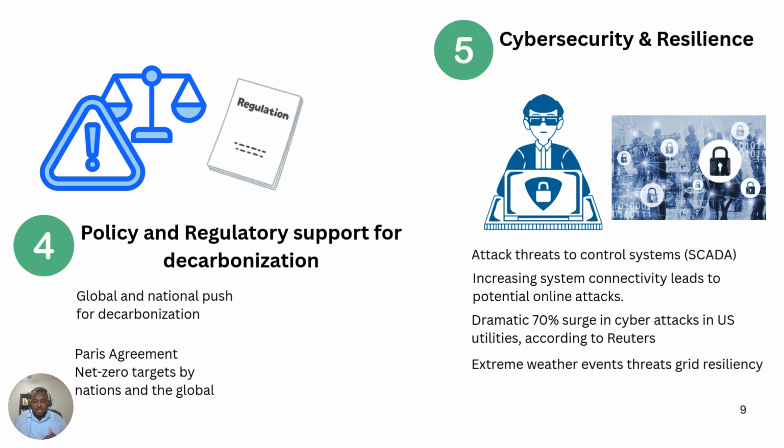So once a plant operating condition is changed, then instead of the plant running smoothly, the hacker can actually trip a circuit breaker. And if you trip a circuit breaker of a huge network, there's a huge loss of generation or a huge loss of load. This will cause an imbalance in the system. And once you have an imbalance between generation and demand, then you see frequency will change. And when frequency changes, this will have a cascaded effect and can cause a huge blackout. So when we talk about cybersecurity, you need to think about it that way.